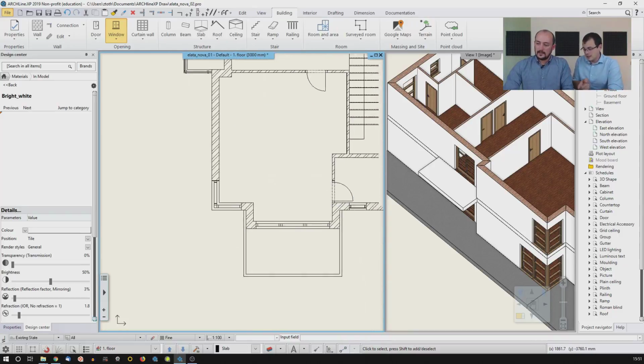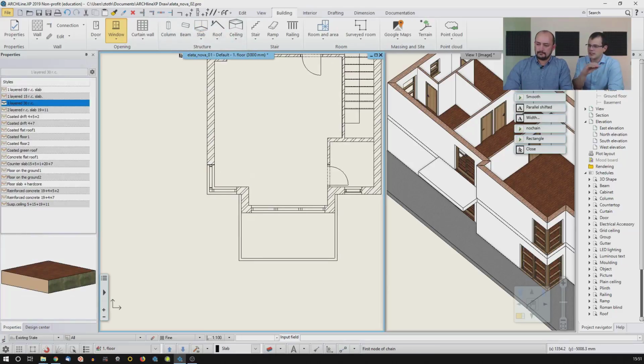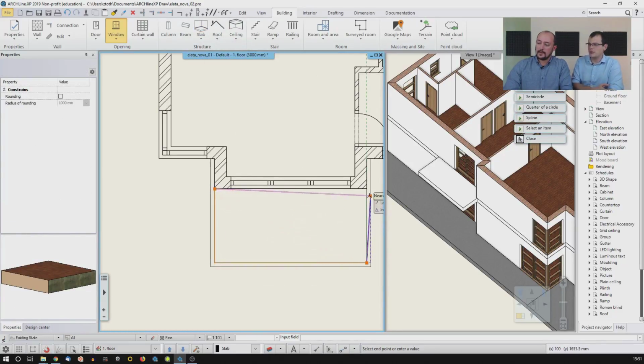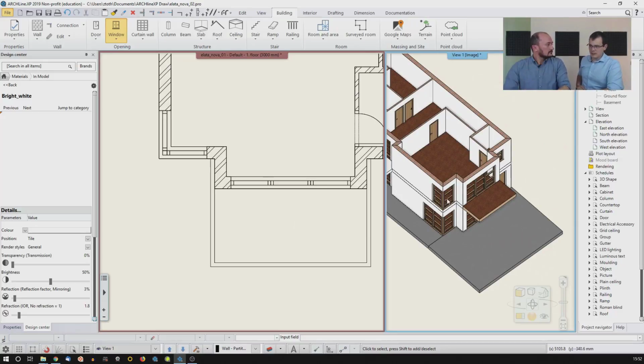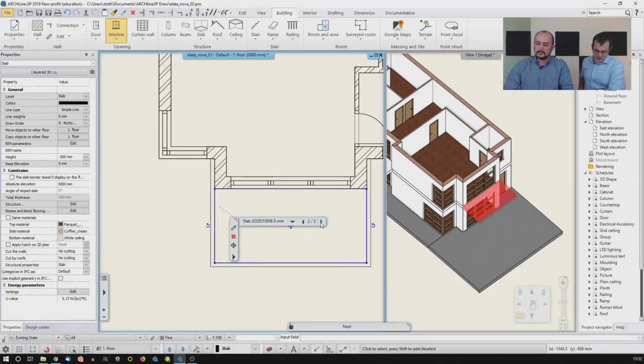So if we go south, then we see that there's a very interesting roof-like thing over here, which we have to copy. So what we are going to do, we do 2 slabs on top of each other. The one on the bottom, we have to set up the correct base elevation and thickness. So the base elevation is minus 300, so I just change it to minus 300. And the height should be minus 100.